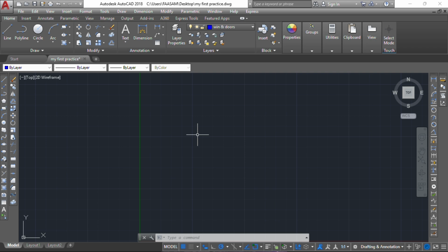As we continue in the class, we'll get to know more of the measurements like that. So now for doors, if you want to create a door for our plan or elevation, the width of our entrance door is always 1.2. The entrance door for a residential building is always 1.2. But for commercial or public buildings, it can range from 1.2 to 1.8 or even more, depending on some factors to be considered. But for a residential building, the width of our door should always be 1.2.